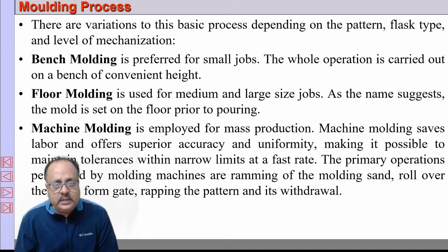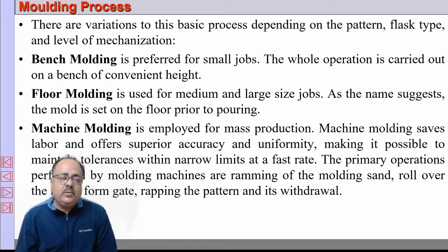Then we have floor molding. In floor molding, we carry out molding of medium to large size jobs, and it is carried out in the floor itself, normally made of sand. And then we have pit molding, where we make a pit in the floor and the pit is lined with fire bricks, and we carry out the molding in the pit itself. That is mainly for large castings. We use cranes for lifting the molds. That is called pit molding, not listed out here.